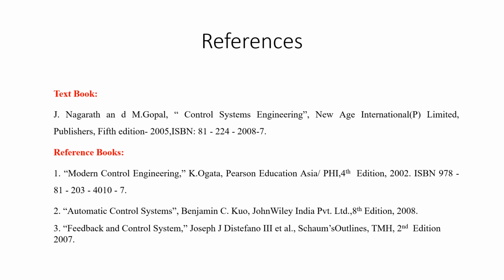The most important factor that we need to consider in block diagram representation is that simple block diagrams can be very easily reduced using the reduction rules, but when we come across a complex block diagram, it is very tedious to apply the reduction rules to evaluate the transfer function. To solve this problem, next we have taken another technique where block diagrams are represented using the signal flow graph.